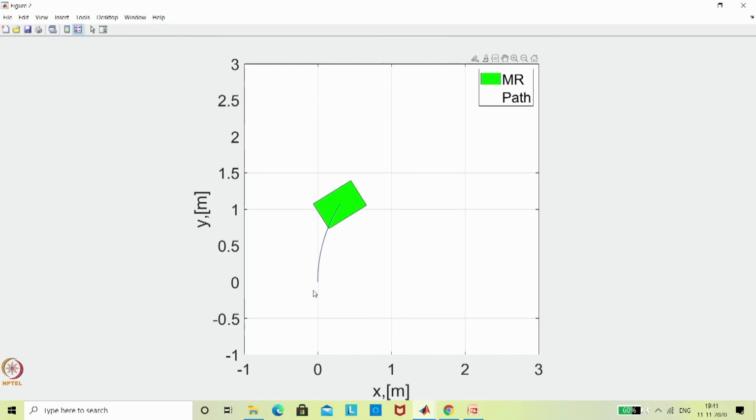Your desired and actual both start from 0 and it is making a circle, but one can see that it is not completing it. Why is it not completing? Because we have not given the psi desired dot as per the circle. We have given it the other way around. Here, how the psi desired is supposed to be is a minus of this. Why is it so? Because it is rotating in the other direction. That is what we have to see. If I change it to minus 0.1 times of t_i, then you can see that it will align with this, but that is nevertheless not important.